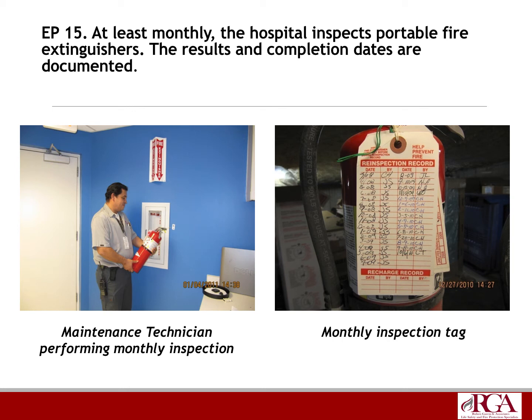And you have to heft it. See, the maintenance tech there is actually carrying it, because the gauge itself, although it could be green, could be a faulty gauge. So you want to lift it up to make sure it actually feels like a 5-pounder or 10-pounder or 15-pounder.